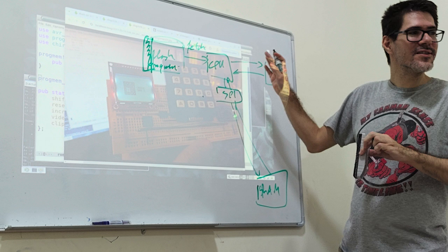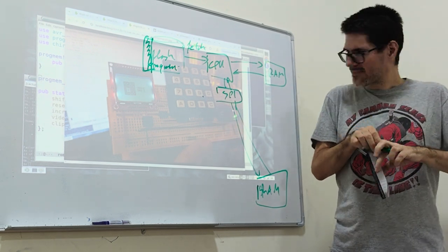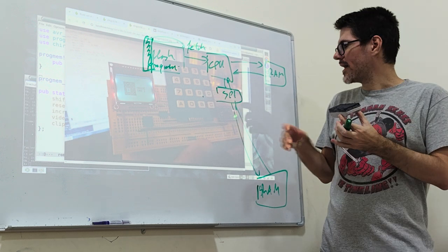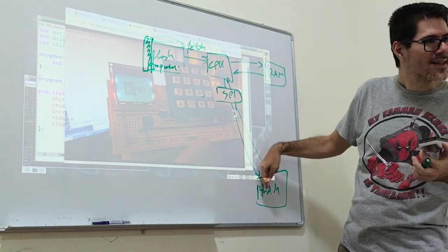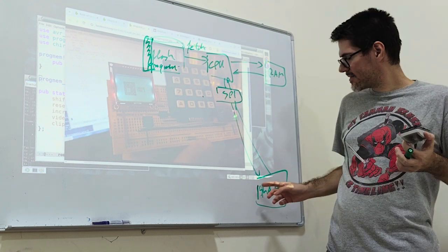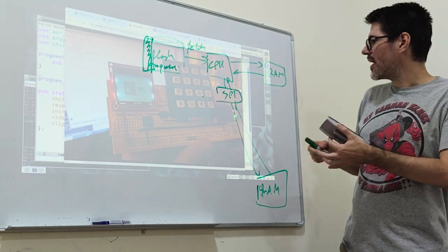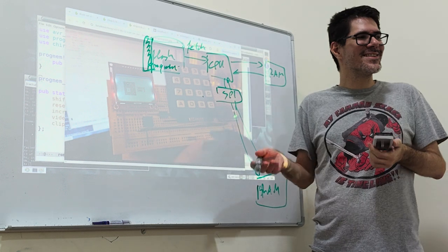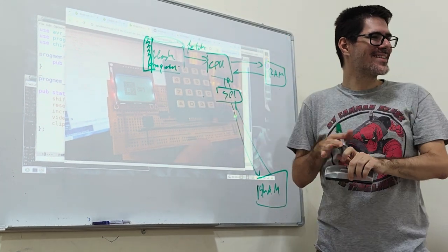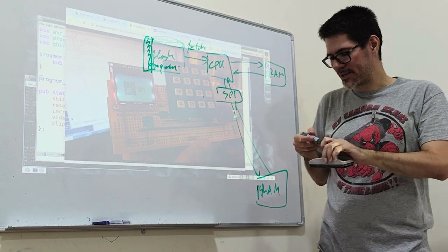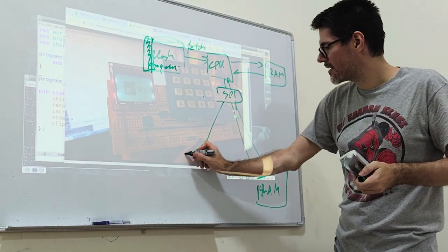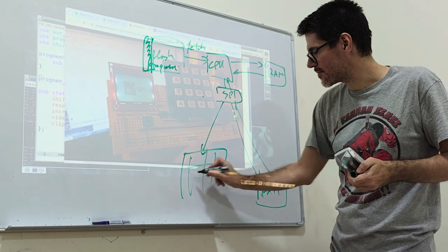Right? And this is orders of magnitude slower because it's SPI, I think it runs at a couple hundred kilohertz or something like that. And it's a 1-bit channel, so you send in 8 bits to change something here. But it doesn't matter because the original computer was so slow. All of this is going to be way faster than what you had on the original machine. And then, of course, we also use the SPI to draw on the screen.